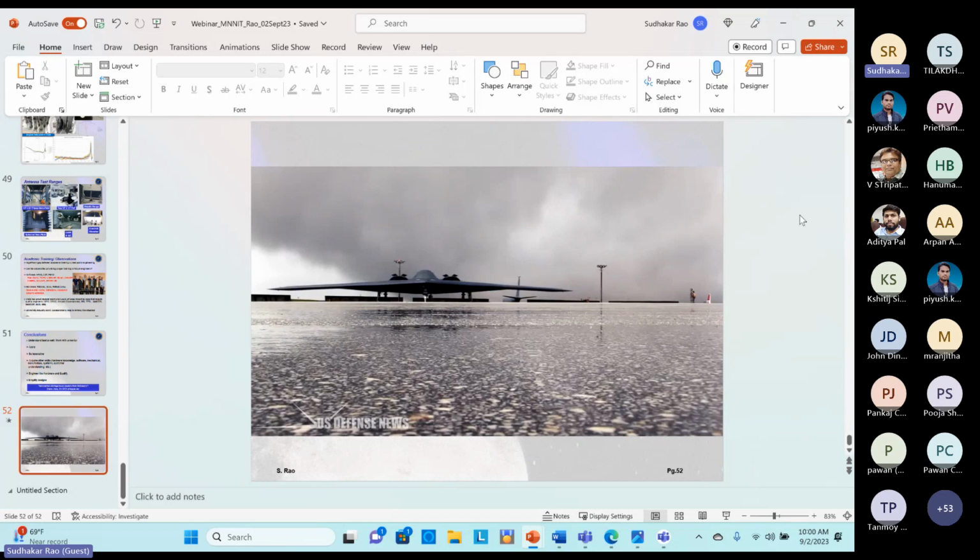The only thing is, since the element is large, your element pattern rolls off quickly. So you want to make sure that you minimize the losses when you scan the beam to 9 degrees. You can estimate that very easily with the Gaussian beam analysis. You can refer to my paper; I think all the equations are there. So you can design any phased array with square lattice or hex lattice with defined grating lobe location, defined coverage and frequency bands.